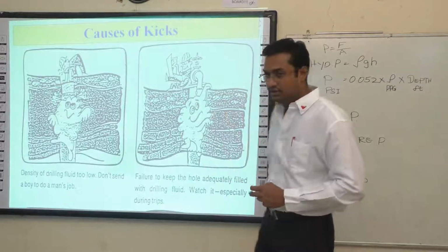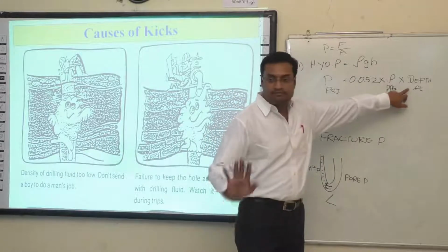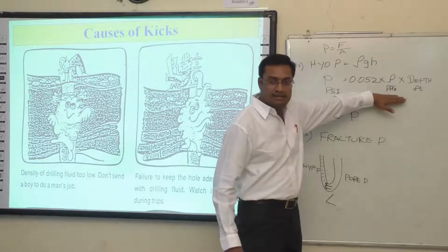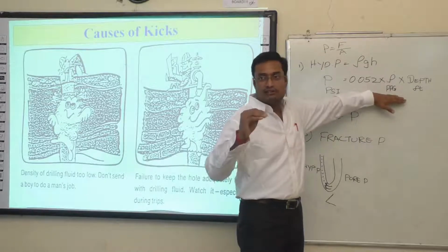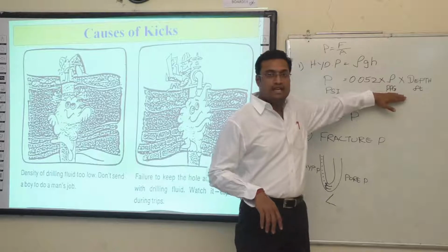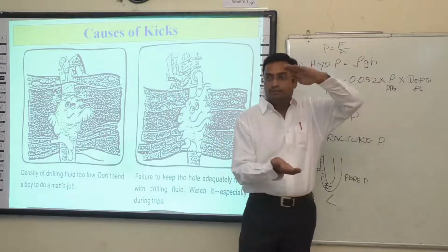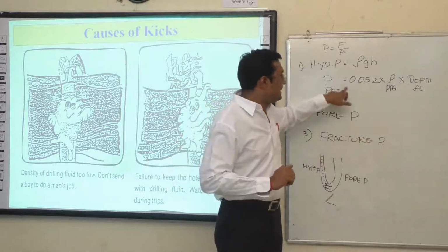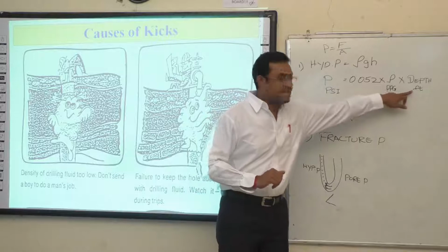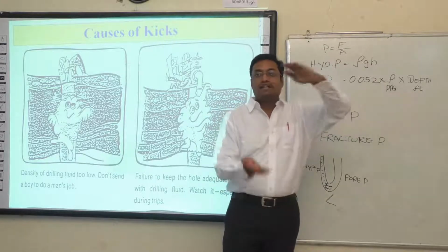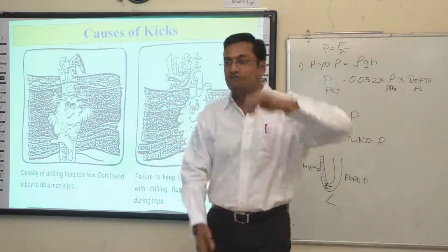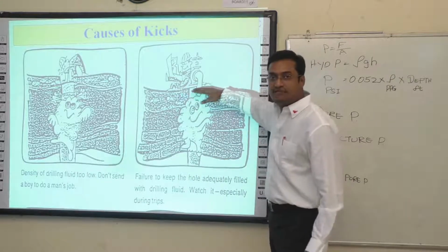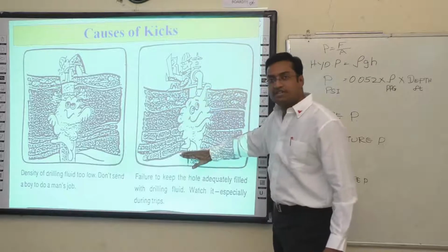The next is, we have the depth. We have the depth, feet. That means, even if you have the right density, or even slightly higher, if the depth becomes less, what will happen? The pore pressure will take control. The depth is not going to reduce, but the height of the drilling fluid. If you don't maintain the drilling fluid till the surface, the hydrostatic pressure at the bottom will reduce.